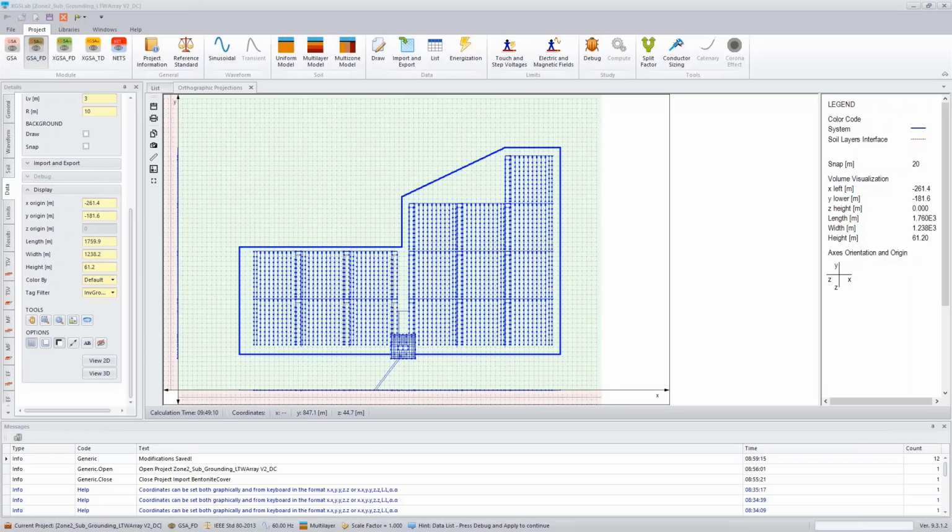One of the questions that came up is that in some designs, they have an isolation between the DC and the AC side of the inverter. Often in these utility scale photovoltaic systems, we'll see that they are grounding the metallic components of the site, which would include the track array. So in those situations, we would see this kind of larger grounding system. Also, where your fault current source is coming from dictates whether or not there will be a ground potential rise associated with that, and then inherent touch and step safety issues.